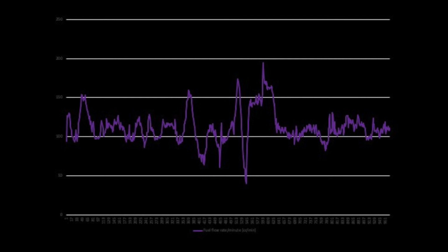So with the speed fixed, we can see the variation in the fuel flow as the vehicle traverses the undulations and hills in the road. As we approach the hills, the fuel flow increases due to the increased torque applied to the engine, and the ECU will compensate by increasing the fuel flow. On the flatter sections, you can see the smaller variability in the fuel flow as the fuel flow adapts to the conditions of the torque applied to the engine.